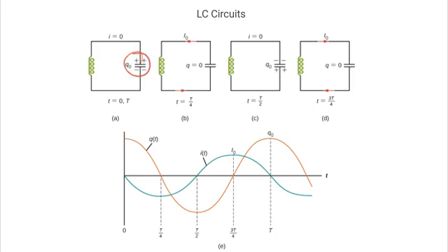So the energy is already here that's stored in this charged capacitor, and you put it into a circuit now with an inductor. So how does this behave? Well, I think it's obvious to see that, because this is now a closed loop, you're going to see the positive charge from this end travel around and end up over here, right? Of course, we know what's actually happening is the negative charge is traveling in the opposite direction, but the direction of our current is always the direction of the positive charge, so you have a current that's going in that direction. Now, this current is going to change because you're essentially going to get up to a point where you get to a maximum current, right? It's going to take some time. The inductor is impeding that flow, right, as we expect it to do. So the current starts off at 0, but then sort of builds up to a maximum amount of current.